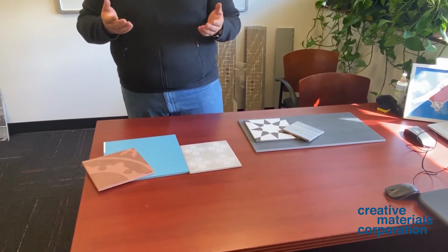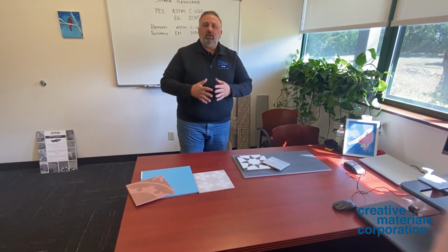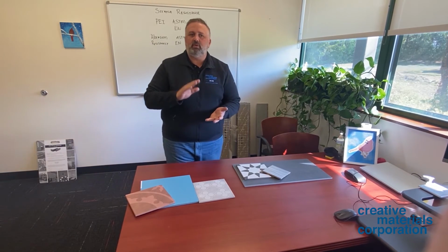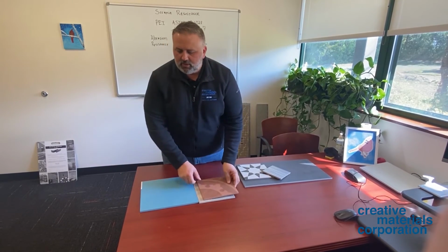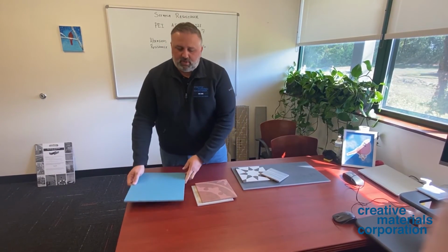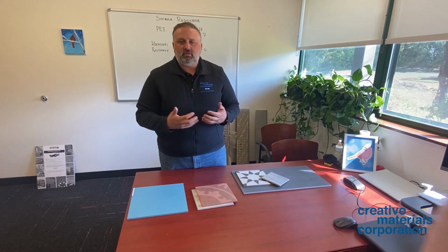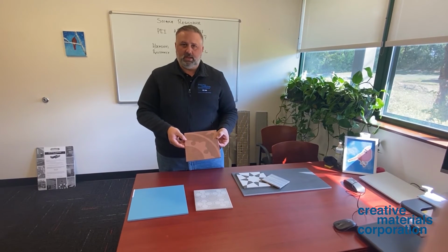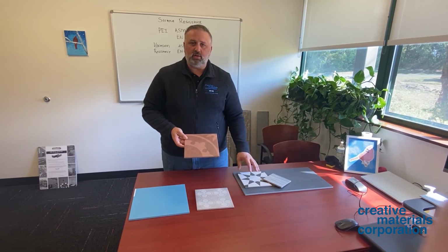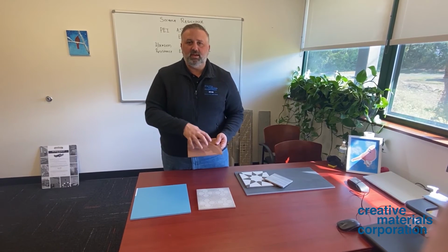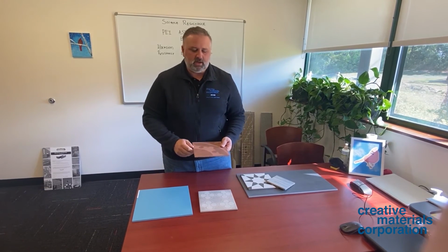So really what this allows for us to have is a wider selection of aesthetics considered unglazed to be used in heavy duty traffic areas. If you're going to use tile in airports or train stations or heavy duty, still recommend the traditional through body tiles, which are again this kind of tile. But if you're looking for tile that has very strong surface against scratching, now look for unglazed as opposed to glazed color body or glazed non-color body. That's our recommendation going forward. It'll open up a world of aesthetics to you with the same technical characteristics as the traditional through body.